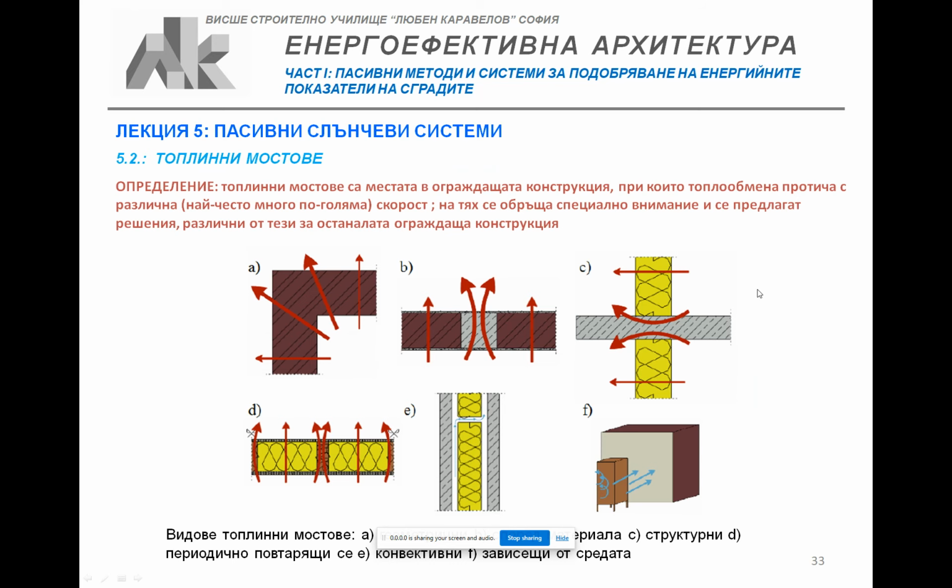The third kind of thermal bridge is structural thermal bridge, when an element goes outside with some of its surface, such are balconies or parts of the walls that separate balconies between the neighbors, or when for some design reason building is designed in sectors, and the different sectors are not in the same row but go in front of the other sector or a little behind it, and there are again walls that face in some of their parts the outer air, and the next part goes inside the rooms.